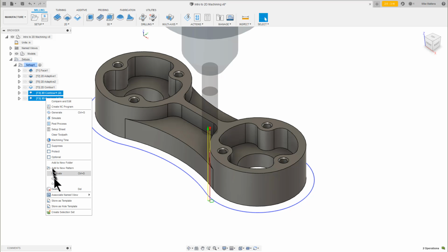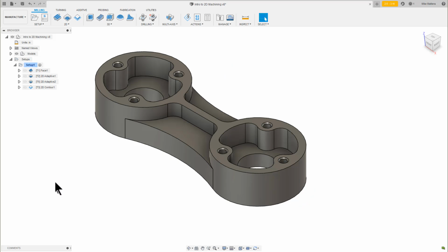There is something a little bit better. It's called a derived toolpath. Derived toolpaths let you copy the parameters of an existing operation and use it in a different type of toolpath. But you can also use it for the same toolpath. It will bring all the geometry selections, tool selections, and the parameters, like a copy. The best part is, after it creates the new operation, it opens it for editing.